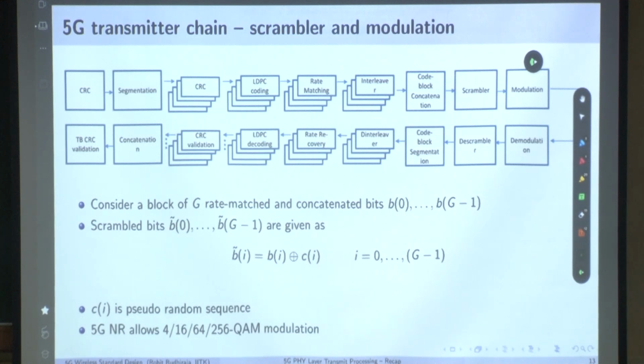The digital to analog converter converts this digital bit stream into an analog waveform, and that analog waveform needs to be up converted to the band which is allocated to a particular operator. That is called the RF up conversion. This plus some other modules plus this DAC is implemented on one platform. The other is called the RF front end, which is implemented on another platform.